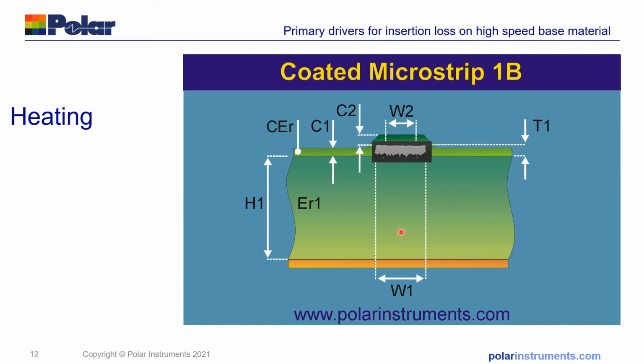So not as smooth as the HVLP5 foils there, but there's a microsection of some copper on a stack up here. Again, if you've got a trace where the roughness is higher on one side than the other, it's worth considering when you design the stack up, should you put smooth to smooth or rough to rough? And that might mean that for things like strip lines, you might want to fabricate a differential strip line, a broadside strip line, across a pre-preg rather than across a core, so you can swap the logic around for strip lines than you'd have for perhaps impedance designs.